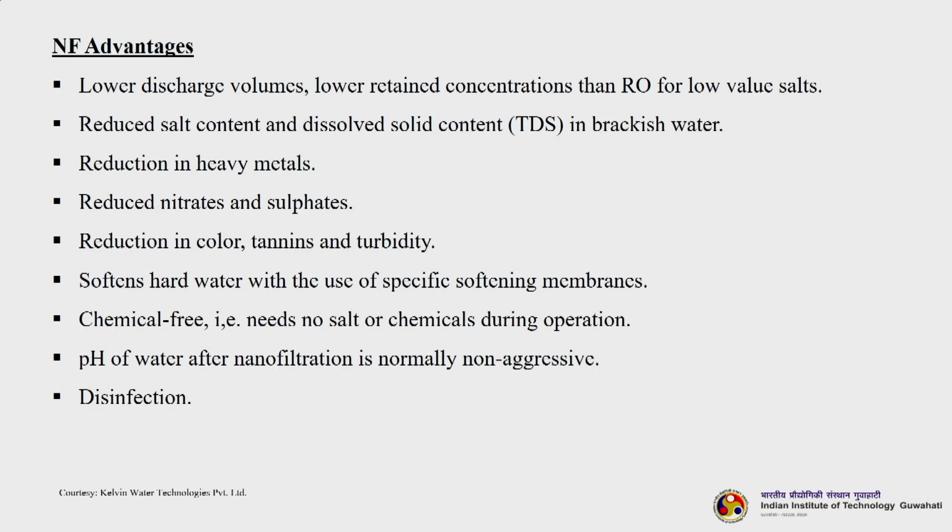So, let us understand the nanofiltration advantages. It has lower discharge volumes, lower retained concentrations than RO for low value salts, reduced salt content and dissolved solid content in brackish water, reduction in heavy metals, reduced nitrates and sulfates, reduction in color, tannins and turbidity, softens hard water with the use of specific softening membranes, chemical free, that is needs no salt or chemicals during the operation, and pH of water after nanofiltration is normally non-aggressive, and disinfection. So, these are the things that are being done by the nanofiltration membranes.